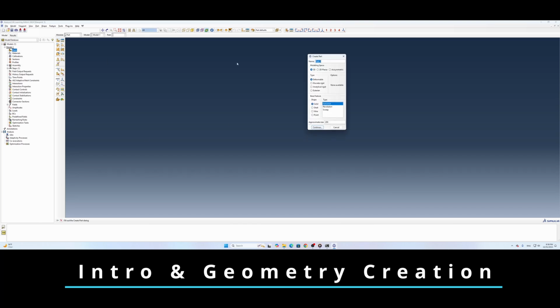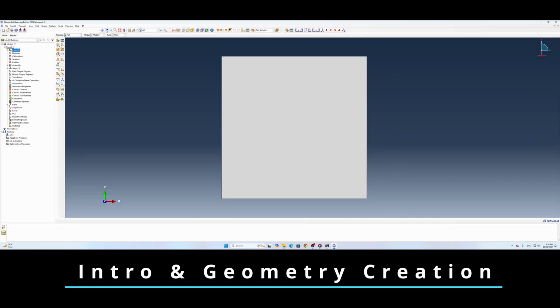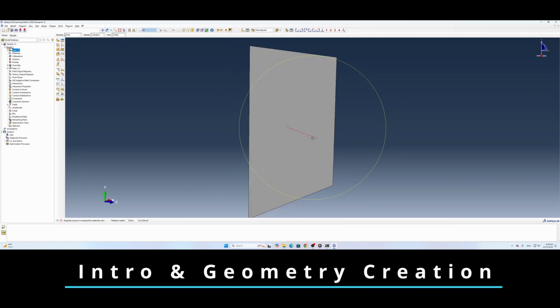Right click, create, and then the name is going to be plate. I'm going to use the shell function, planar, continue. Then I'm going to create a rectangle shape. After that, we can use the dimension function. The plate needs to be 60 millimeters by 60 millimeters, so 60 here and 60 there. And then okay. So now we got a plate. Let's check it. All right, looks good.